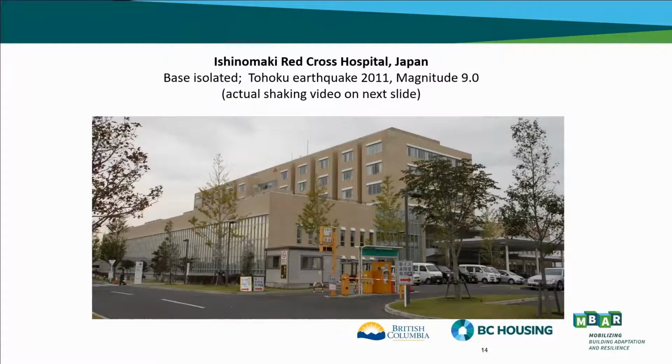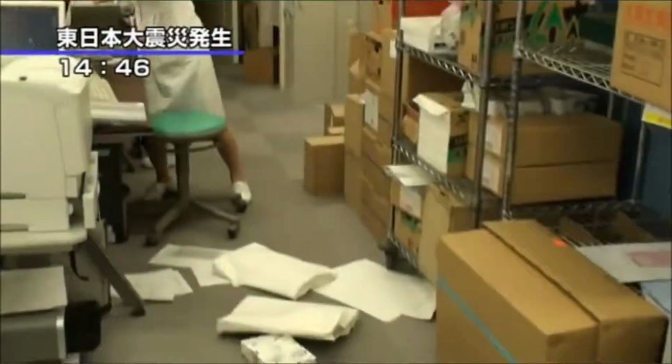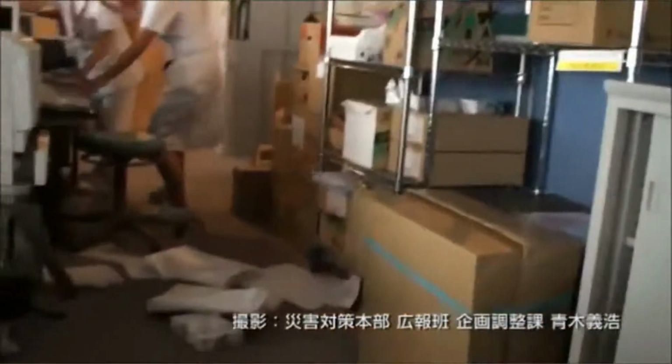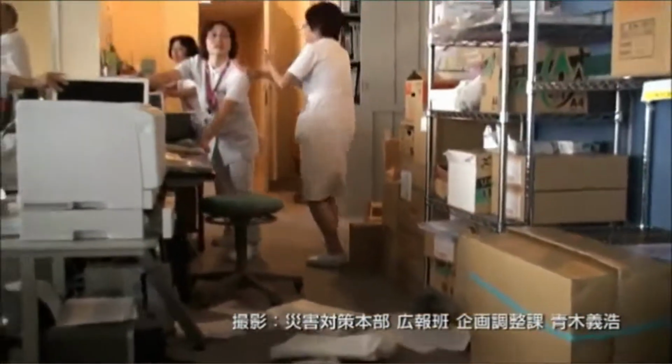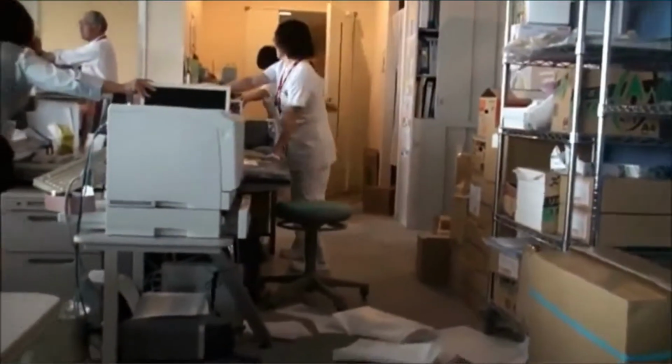This will be contrasted to a hospital that was base isolated in Japan that was subject to a magnitude 9 earthquake. And this video illustrates the significantly reduced level of shaking. There's still a little bit of shaking, of course. See, there's no panic or alarm with the occupants. And again, at the end of the video, there's even a gentleman casually looking out the window to see what is happening around the building. So significantly reduced compared to a fixed base building.